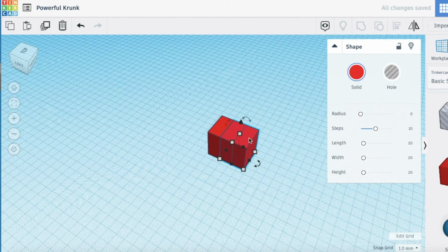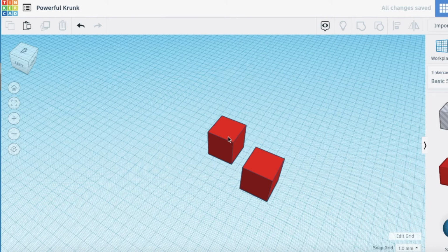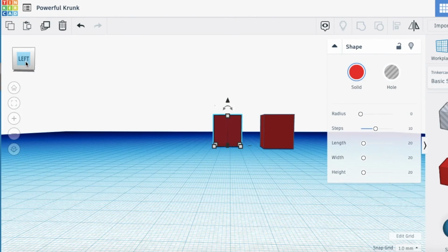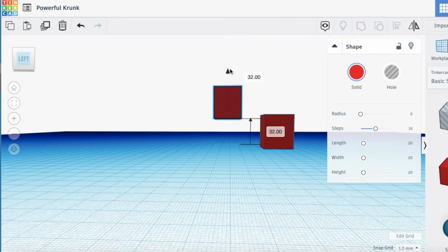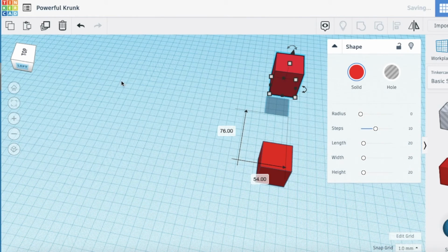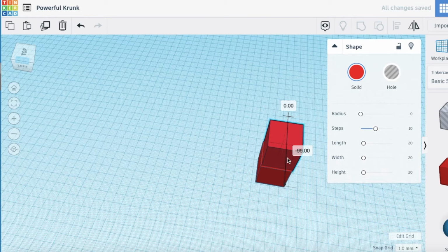Now the cone allows you to lift your shape off the ground and control how high it is off the ground. So let's say I wanted to stack this one box on top of another box. I would just drag the cone up, reorient myself, and then I can continue working to put this box on top. And this is super helpful if you don't want to switch between work planes, if you want to stay kind of on your tabletop and not be using an up and down work plane.